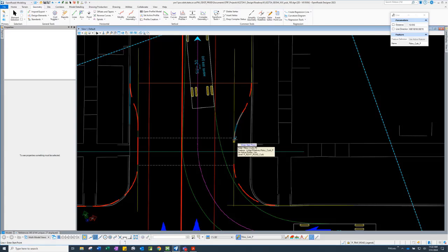And I try to draw so this corner's direction will go from north to east. So I just snap to the end of this line. I snap to the end of this line. And then I snap to here. And I usually come out here and give it a spot because I know that's going to change as I go through the design potentially. But I make sure to do an inline snap or near snap with this construction line.